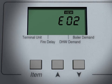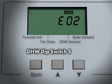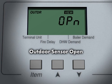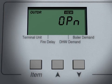Error message 2. This error is caused by an improper DHW dip switch setting. To clear the error message, set the DHW priority off dip switch to off and press the Item button. Outdoor sensor short. The control is no longer able to read the outdoor sensor due to a short circuit. Outdoor open. The control is no longer able to read the outdoor sensor due to an open circuit. In either case, the control assumes an outdoor temperature of 32 degrees Fahrenheit and continues operation. Locate and repair the problem per manufacturer's instructions.